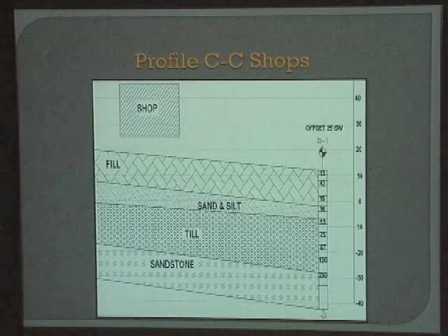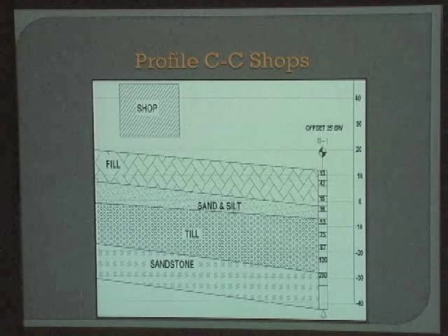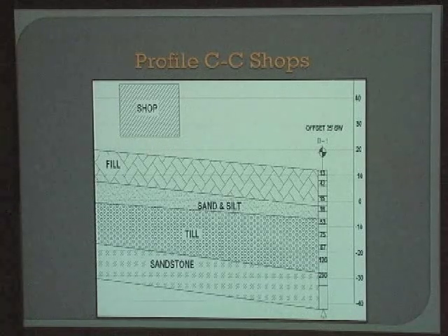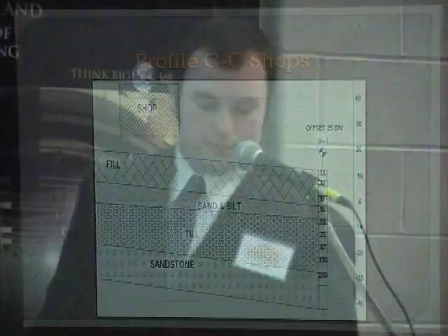From this, the recommended foundations we came up with were shallow foundations that would go into the pre-existing layer of fill, which are then supported by deep-driven piles into the dense glacial till. And now Matt Dunn will talk about our foundation recommendations for our underground parking garage and restaurant.